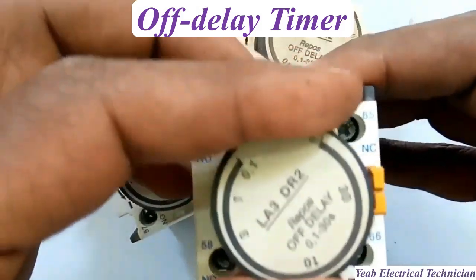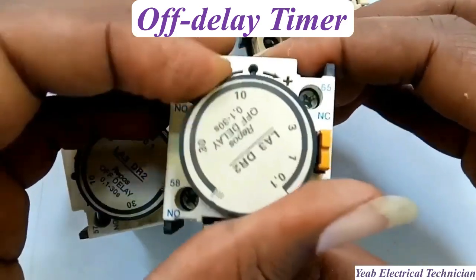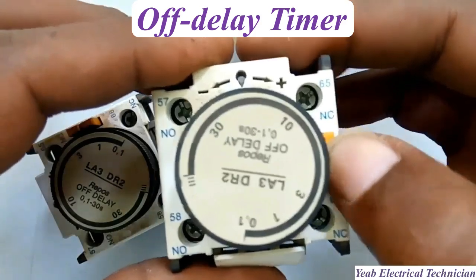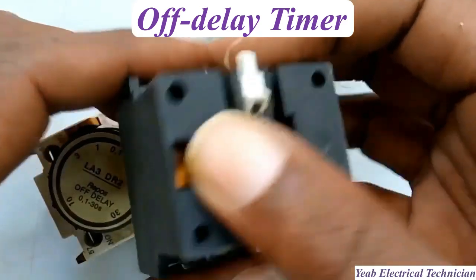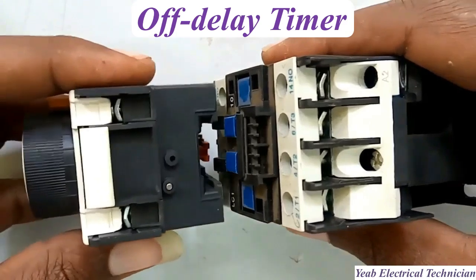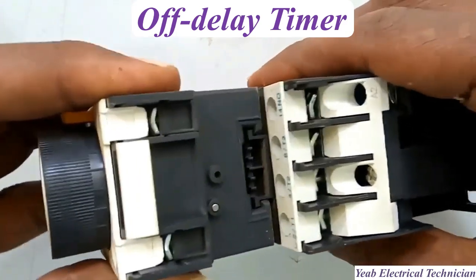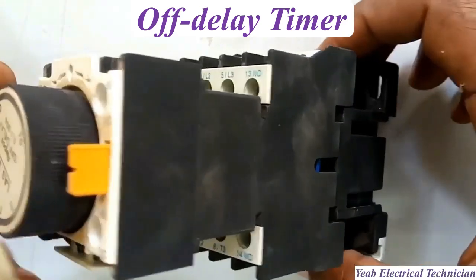An off-delay timer's primary function is to keep a circuit on for a set amount of time after the input signal is turned off. A common example is a ventilation fan in the bathroom or a cooling fan on a machine. The fan stays on for a few minutes after the light is switched off or the machine is shut down to ensure proper cooling or air circulation.